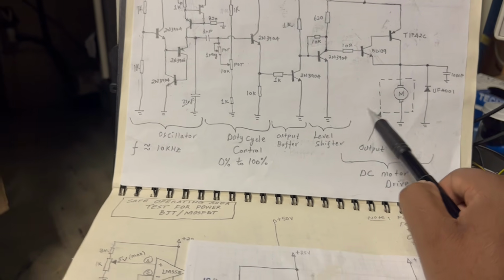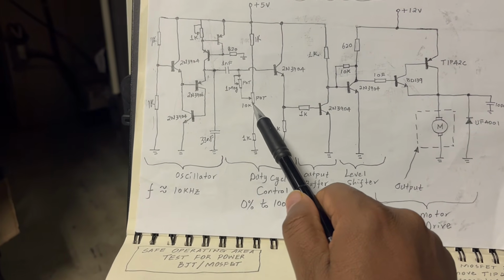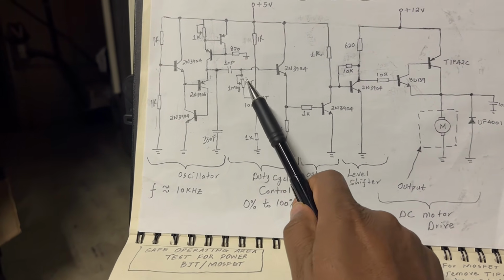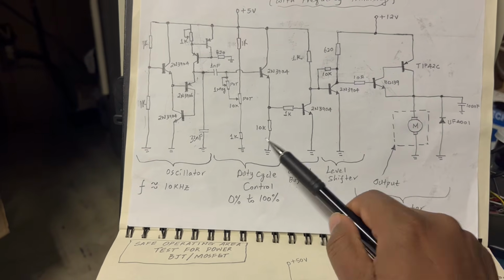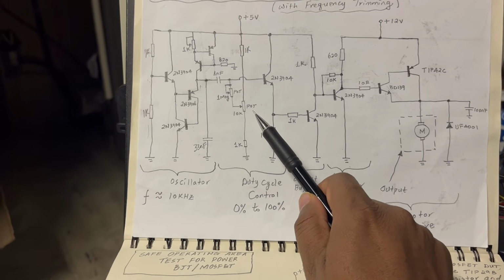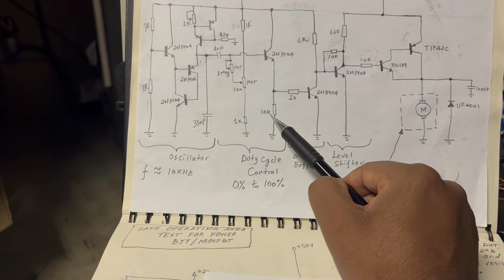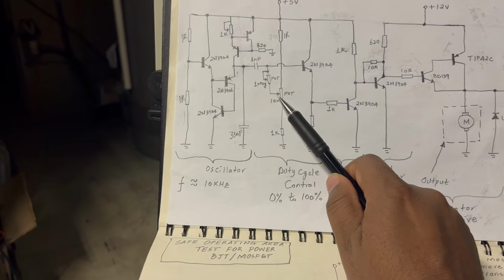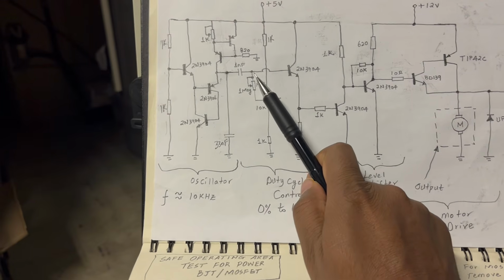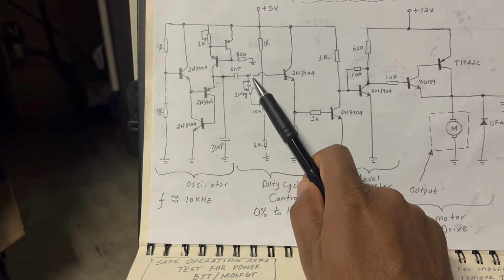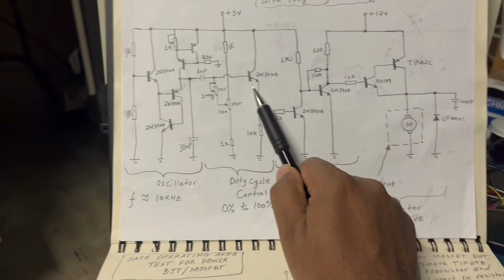That average voltage can be fed back into here and be summed into the voltage that's generating the offset here in a negative feedback fashion. As the frequency goes up, the average voltage will go up, and then that average voltage will be subtracted from the voltage that's being offset into this circuit here, and that will lower the duty cycle, right?